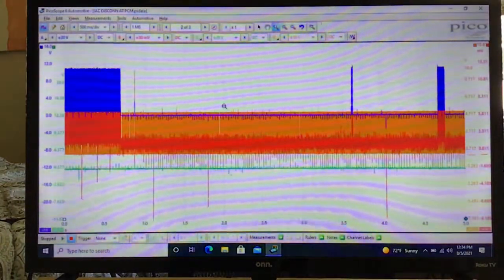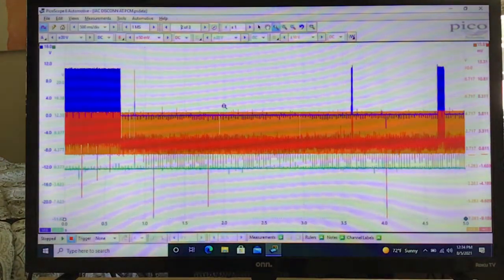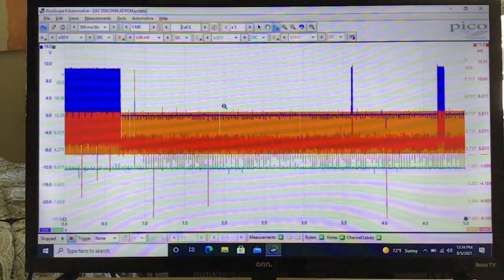It's coming back, folks. If we had a pin fitment issue at the PCM terminal that controlled that duty cycle solenoid, our test point would tell us a lot about where that circuit is open or compromised. So just take a look at that test point. If that became disconnected, our test point would be on the PCM side of the connector, not the IAC side of the connector.